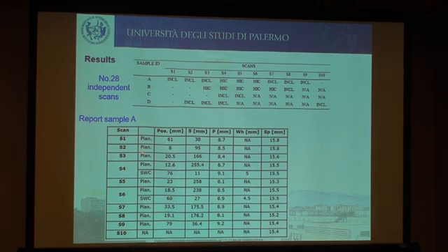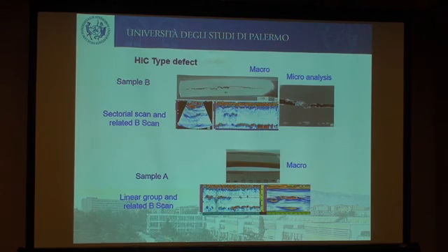As I said before, the type of flaw. So at the end, we had only two types of stepwise cracking. The other defects were also planar defects, with the position starting from 0, so the origin of the plate, the length, the depth, and the height of the thickness of the defect, so stepwise crack. So only for scan number 4 and scan number 6 were these 2 types of defect. So this is the information we got.